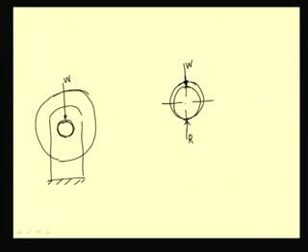Because no slippage occurs at this point, and with respect to this point, this axle tends to move, and so new points of contacts happen, and slowly the axle tries to climb in this direction. So, the point of contact actually shifts, and this happens till some maximum point which corresponds to the impending slippage case, where the normal reaction